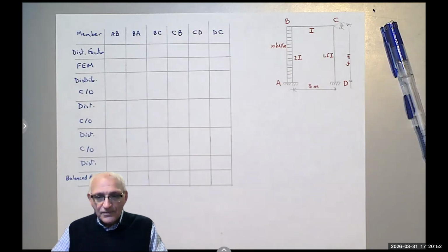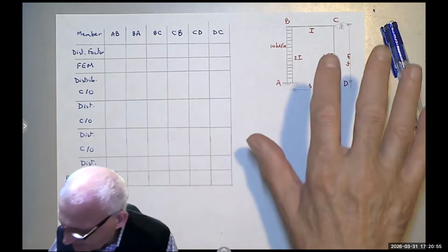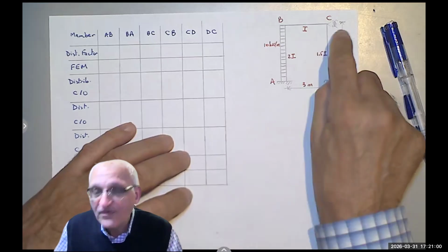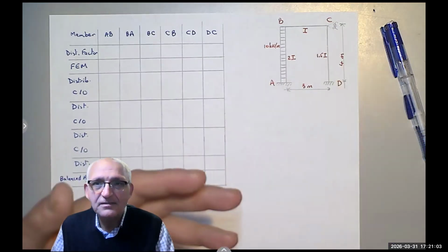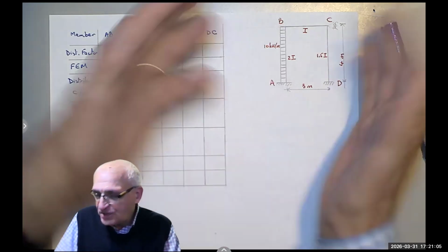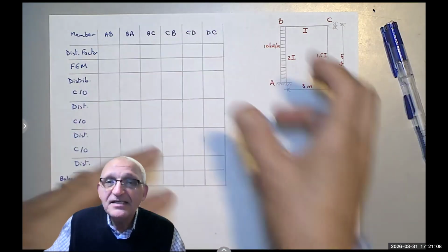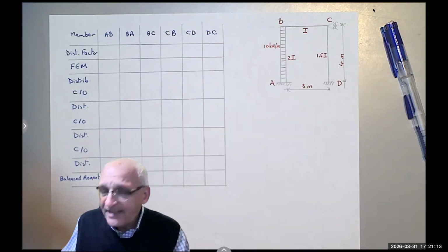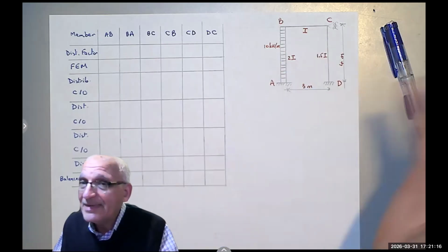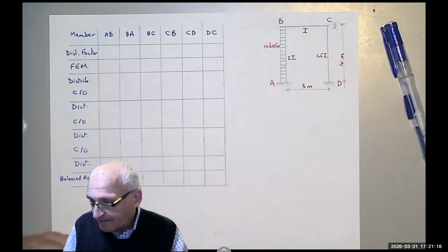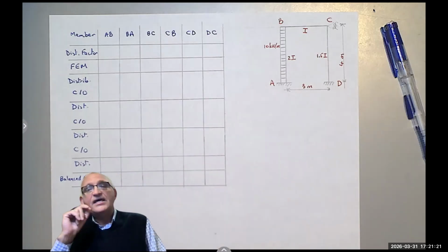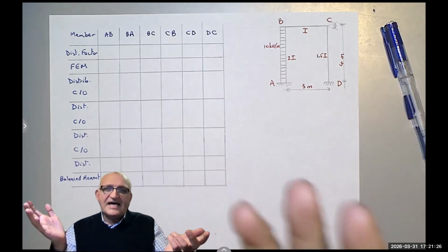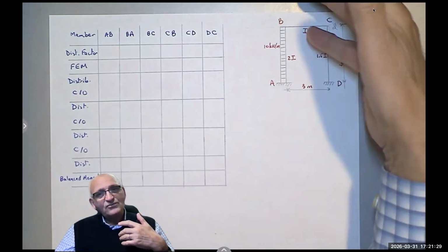And then once I find the different moments, I would use those to find the reaction at that fictitious pin. Then we are going to take all the loads and apply a moment. We'll see why as we go. Based on the moment or moments that we add, we are going to ask what the reaction is due to this moment. Of course, it won't be exactly the same reaction as the one we found in part one.